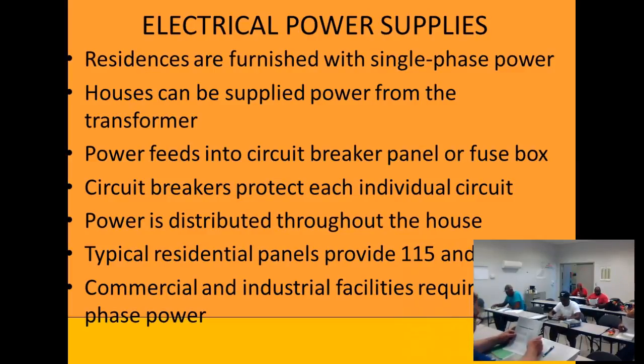The first page, 298, 26-1.1 power source: the voltage available to the refrigeration unit must be within plus or minus 10% of the unit rating for single phase units and plus 10 minus 5 for three phase.